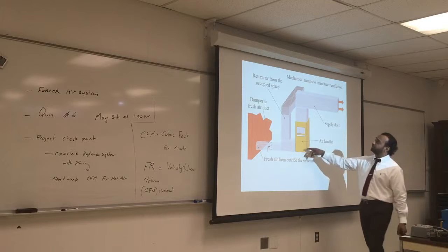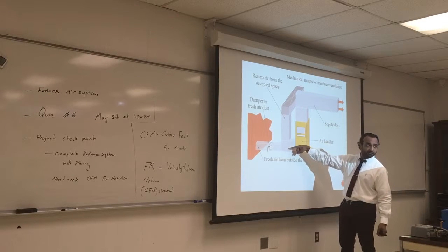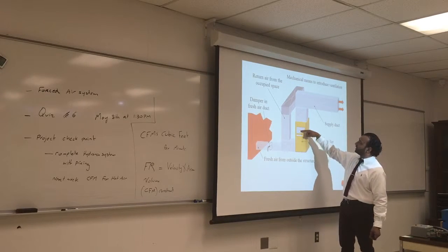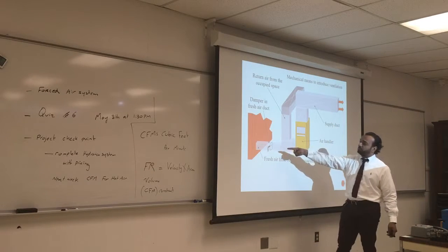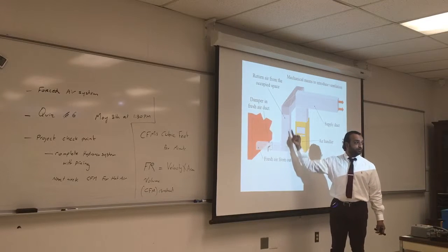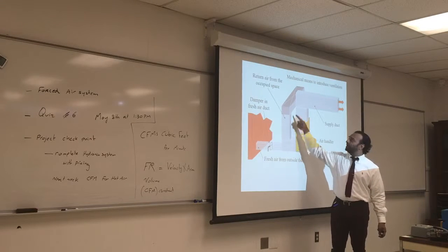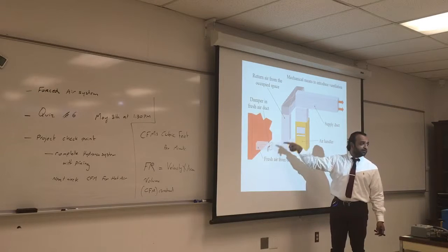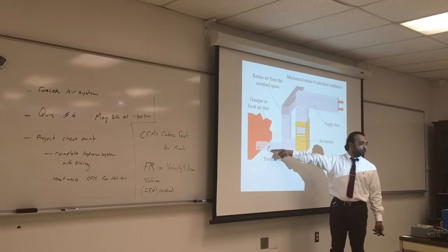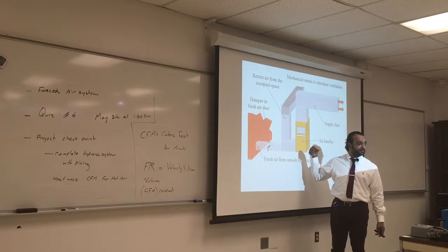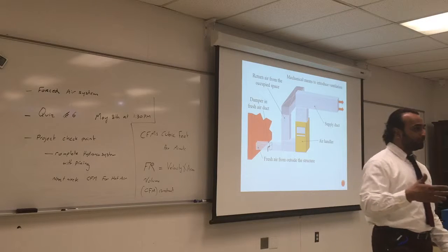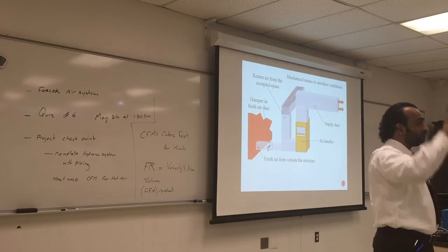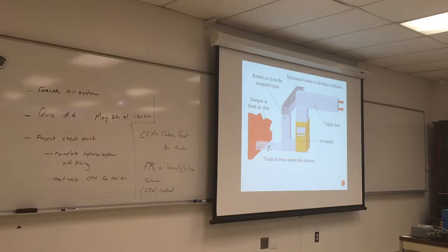You can see this is the air being sent, coming up from the living space, going through the air handling unit and going outside. It's the return air. So usually you want the damper to come with the return air, because this is the direction of the flow. So what is the pressure here? Is it lower or higher than over here? It's going to be low pressure. It will pull in things with it. Same with the flue pipe in an oil burner. Remember the swinging door: as the flow goes out, when air has high velocity, it also has low pressure.